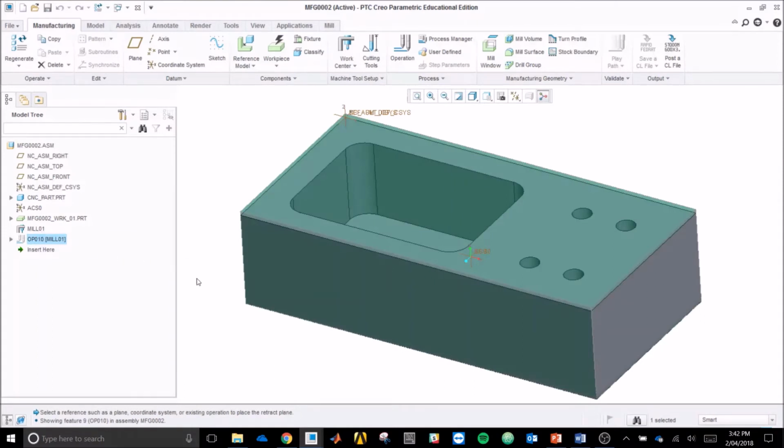But now we can start adding operations and removing material. So I'm going to start by face milling, so removing this 2 millimeter thickness of stock. I'm then going to look at pocketing this piece out using a roughing operation. And finally, I'm going to end that by a drilling operation, where I'll produce these 4 holes seen here.